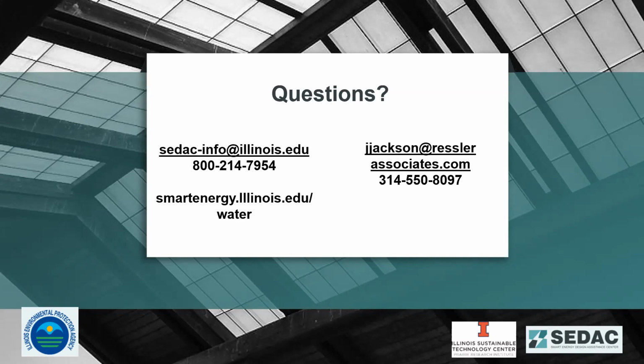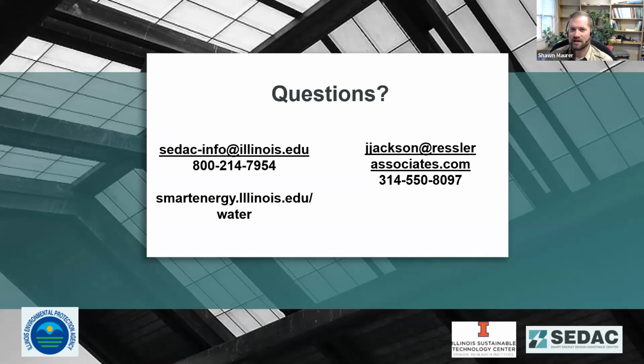We did have a couple questions come in the chat asking about how long you should store history for, like an SQL report or SCADA trending histories. Some of that's going to depend on what variations you're seeing at your plant. Is it fairly stable? Do you have seasonal variations that you need to track? Usually we see back to about a year stored. If you've got the server space, we'll see multiple years, 2 or 3.